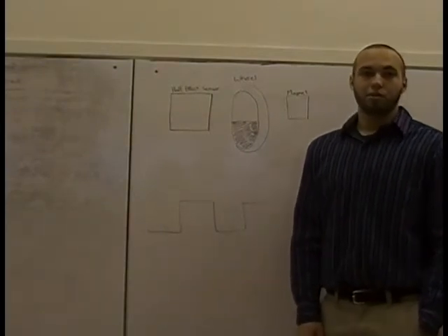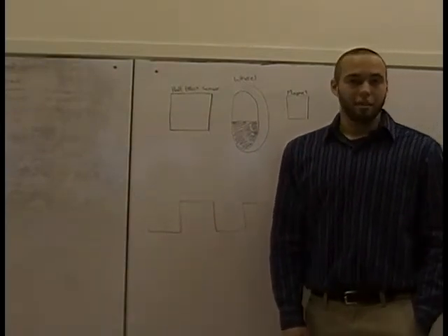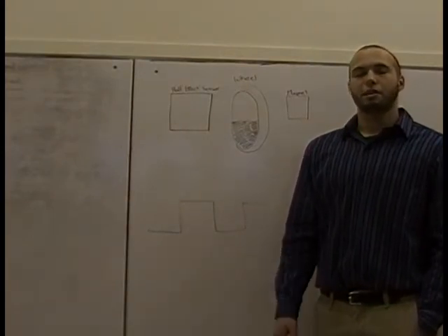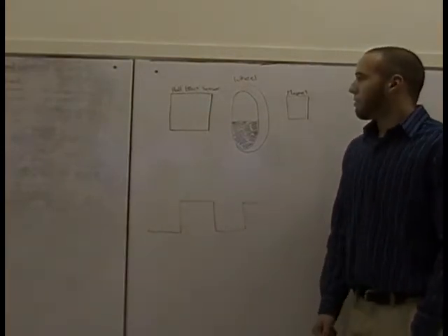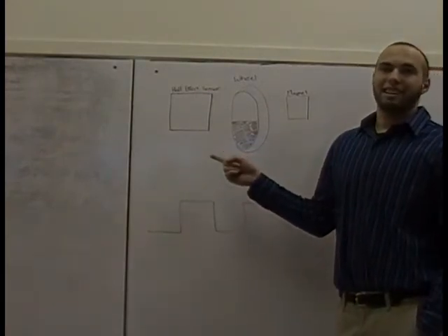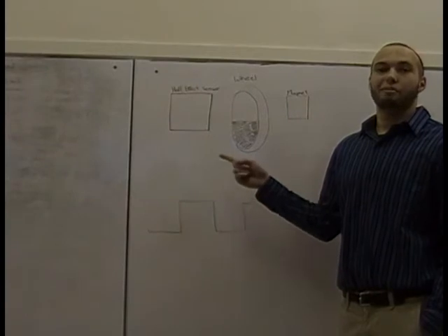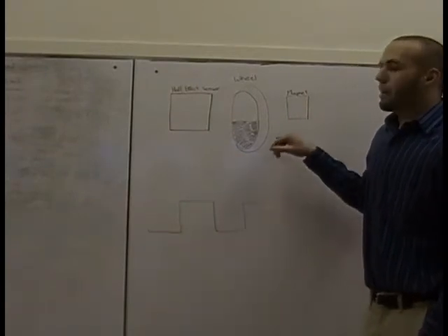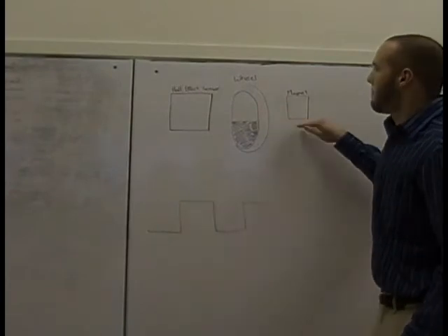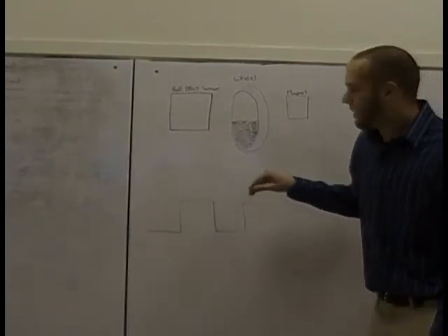I'm going to talk about two of our sensors in particular. That is the tachometer, which detects RPM, and then also the speed sensor, which uses RPM to determine the speed of the bike. For both these sensors, we're going to use what's called a Hall effect sensor. A Hall effect sensor detects magnetic field, and it's basically a digital magnetic switch. So the way it works on a wheel, for example, if you're determining the RPM of the wheel, is you have a magnet on one side of the wheel, the sensor on the other.